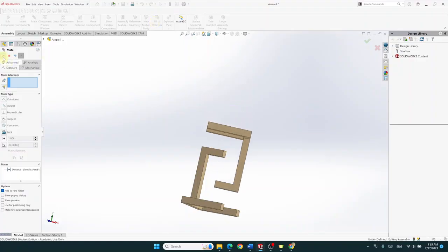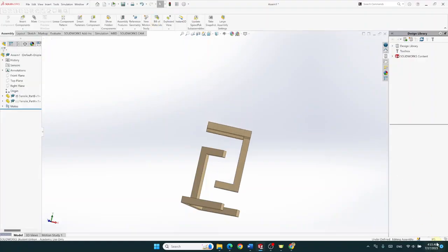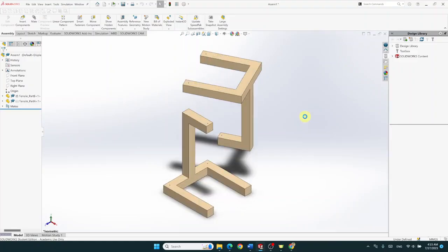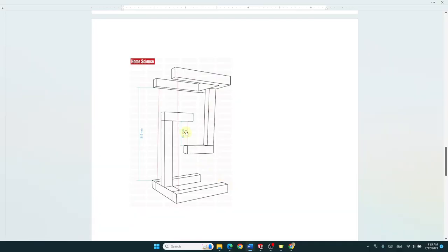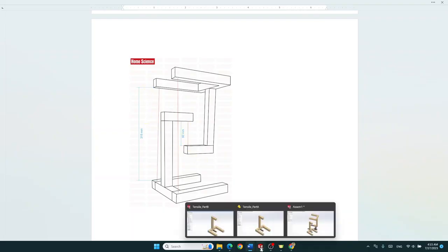And okay, here we go. I forgot to do something there. Just click on there and click also millimeter. So the distance will be in millimeter. So now I have the 315 between this one, and if you click on mates, there we can see this distance. That's the 315. Another distance that we need is, okay, this 92, that should be there. We should not have to do anything with that, because if it's 315, that should be 92. We can check after.